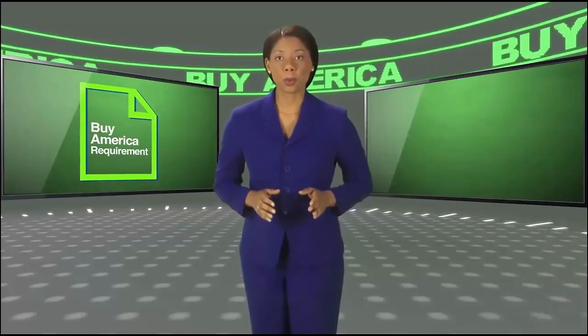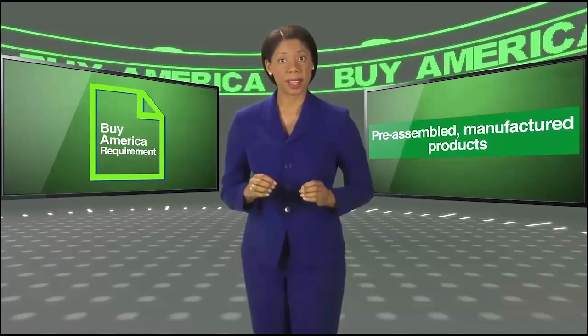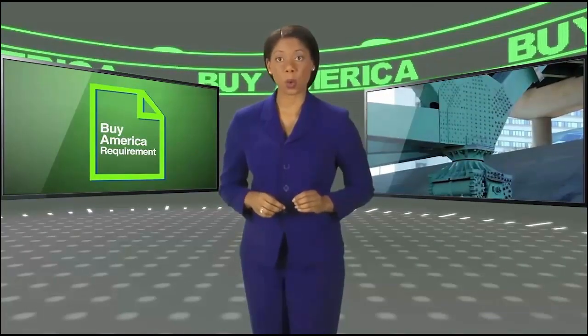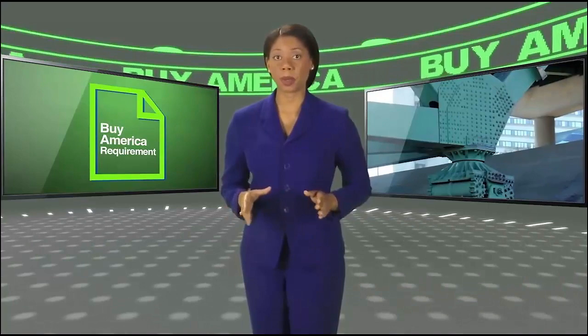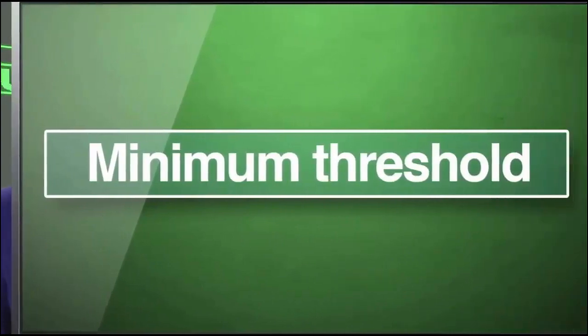The Buy America provisions specifically address pre-assembled manufactured products that contain steel or iron components. Your contractor should identify steel or iron components of any pre-assembled manufactured product. When this is the case, the company who completed the assembly should provide the appropriate certification statement of conformance with the Buy America regulation. You need to track the value of those components in contract administration records if certification statements are not provided, to avoid exceeding the minimum use threshold.